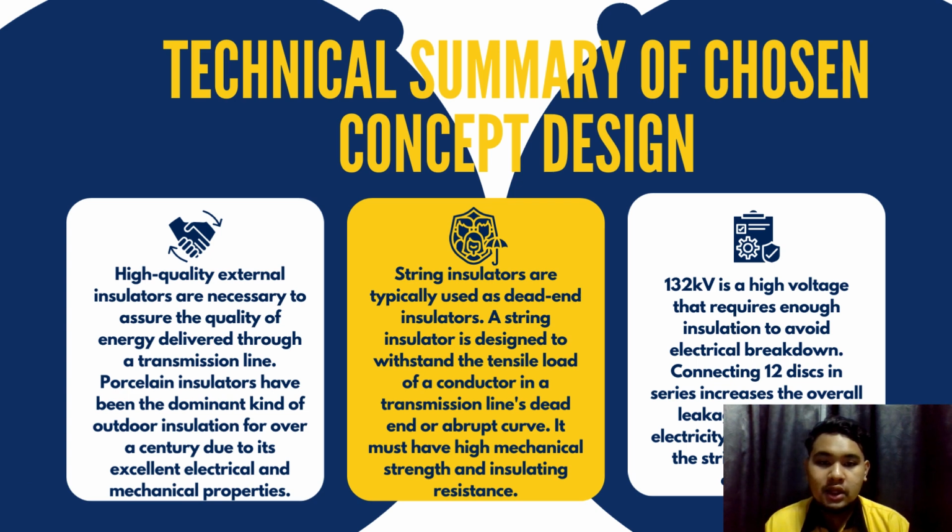Next we go to technical summary of chosen concept design. High quality external insulator are necessary to assure the quality of energy delivered through a transmission line. Porcelain insulator have been the dominant kind of outdoor insulation for over a century due to its excellent electrical and mechanical properties. Next is string insulator are typically used as dead end insulator. The string insulator is designed to withstand the tensile load of a conductor in a transmission line.